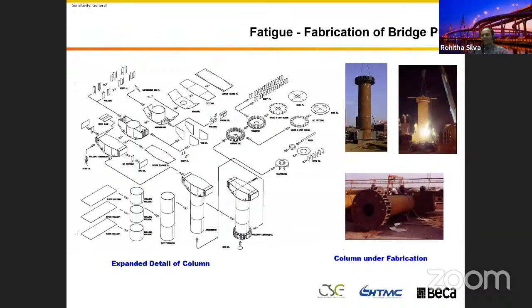I can check the design standard and have a close look. If there is a clause in there, I can send it to you, because I think the curvature in the bridge is not the factor, because it's the reversal stress in the structure that causes the fatigue. Yeah, I can check that for you.